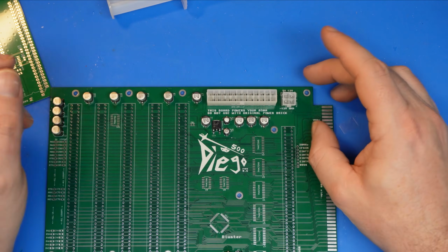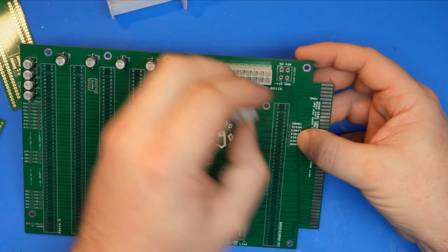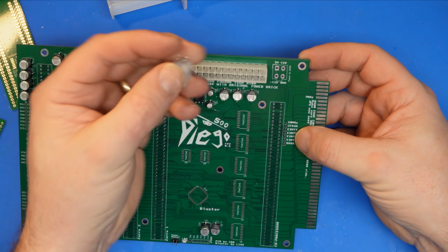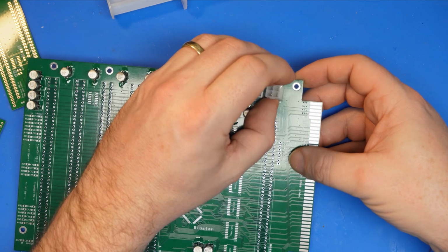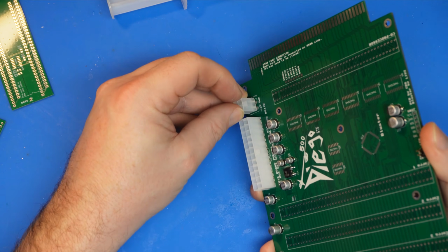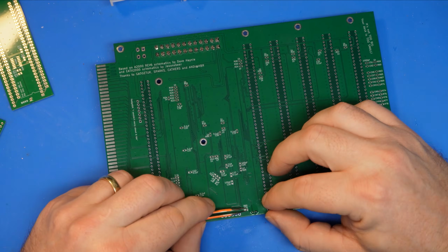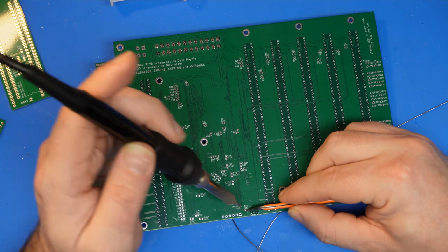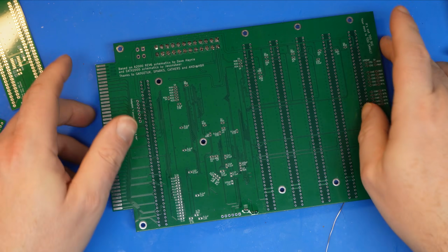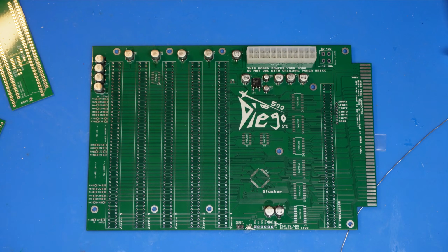Oh, and there's one of our first problems. That doesn't fit that footprint. I mean, the footprint of the package is correct, but the position of the 4 pins is not correct. Nope, that's a problem. Right, we'll leave that for now. Okay, let's try and put some power through this. And we'll just measure a few voltages before we do anything else.